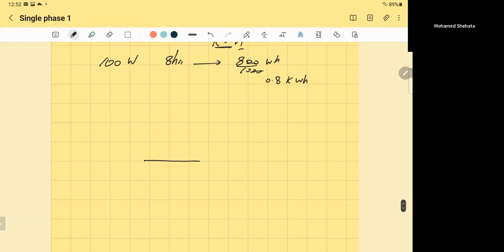If you have the power consumed, or real power, or active power, P, it's horizontal. And the other one, imaginary, as you said, will be in this direction. That's Q. And that's the total power, or apparent power, S. That's what appeared to everybody that consumed. But this P is only consumed, this Q is used, and S is the total used and consumed. So the ratio between P and S is the power factor. It's the ratio between consumed power and total power taken from the supply. That's how they make the penalty.